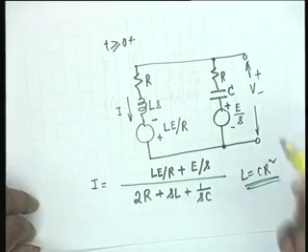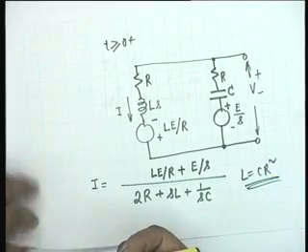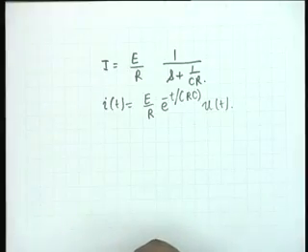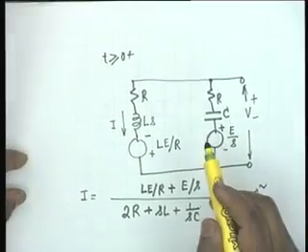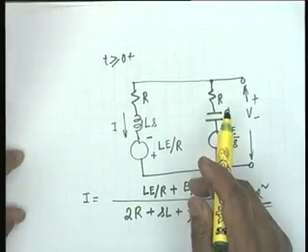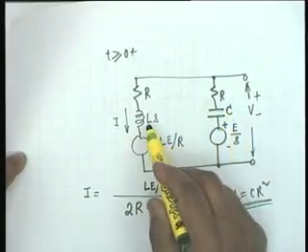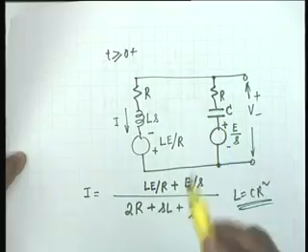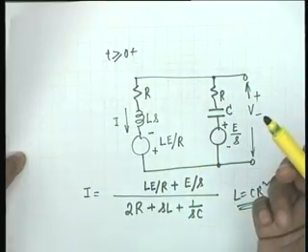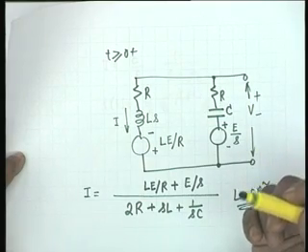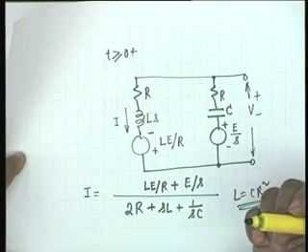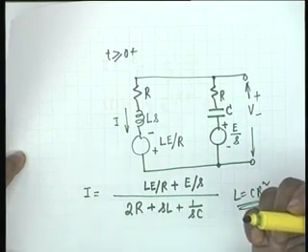So ultimately one factor in the denominator is left, and it is a single pole circuit. The circuit is called a degenerate circuit because even with two dissimilar energy storage elements, it shows only one time constant, and therefore it is a degenerate circuit.